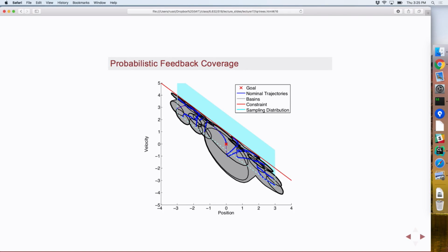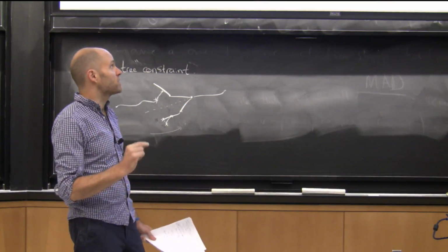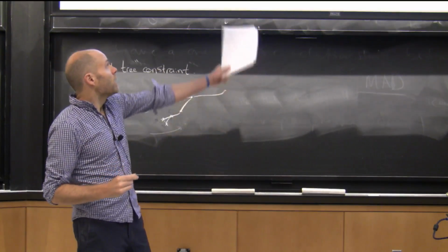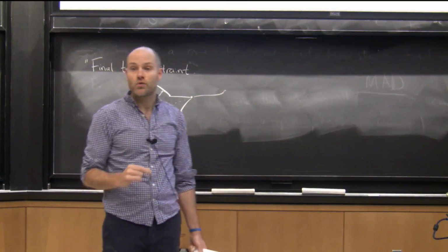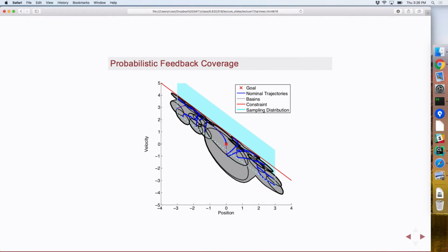But of the set of initial conditions which are stabilizable, you'd like to try to cover them with a feedback controller. And this algorithm has the property that, however inefficiently, just like the RRT, it will eventually draw a sample from any set of the stabilizable initial conditions that has measure greater than 0. It will eventually be close enough, given some assumptions about the trajectory optimization being not too bad. It will eventually be able to connect to the tree, and whenever it connects to the tree, it will come up with a feedback controller that is locally good and will eventually fill the space.